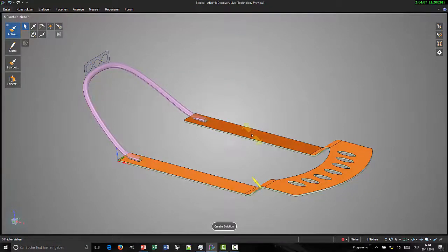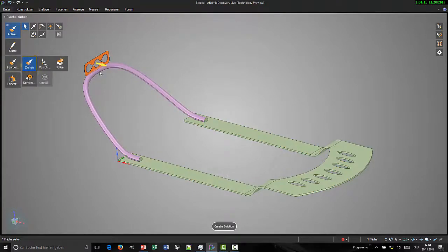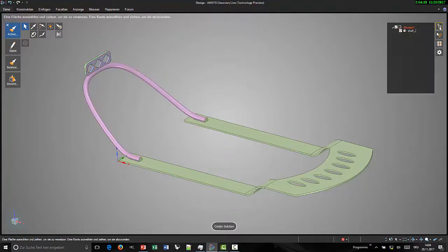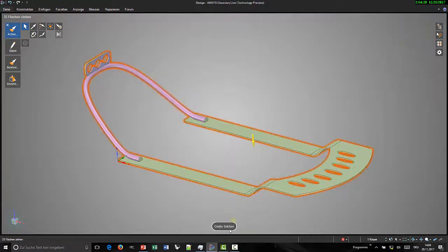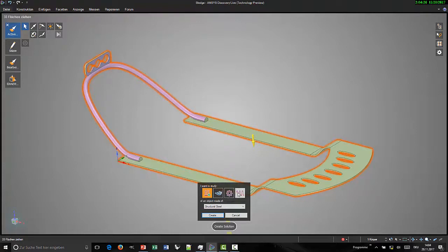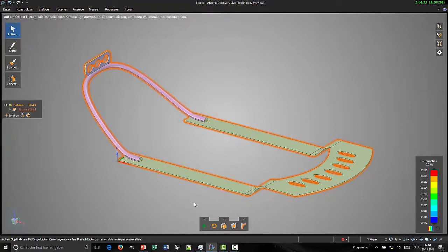Because they are only faces, I need a solid structure. And here I simply add some values for extruding the surfaces to form a solid object. So you see, in the end we end up with one solid, and then there's a nice feature of having simulations within your SpaceClaim as an add-on. There are thermal, stress, modal, and so on, and we will select modal analysis.